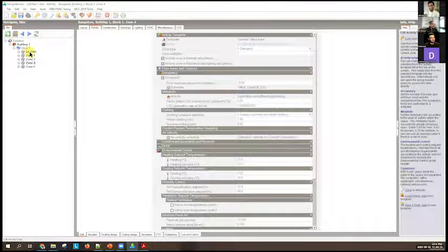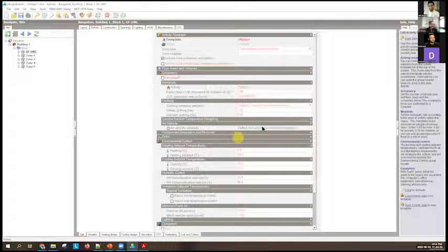Now this ground floor is unconditioned, and it's not really a standard zone. So there are two options. Either we can switch off everything, or we can call it a semi-exterior unconditioned zone. I'll show that to you in a second as well. So it removes all these air conditioning bits and pieces from that zone.